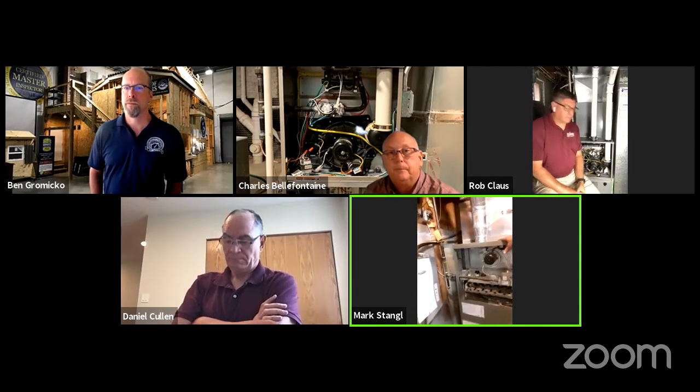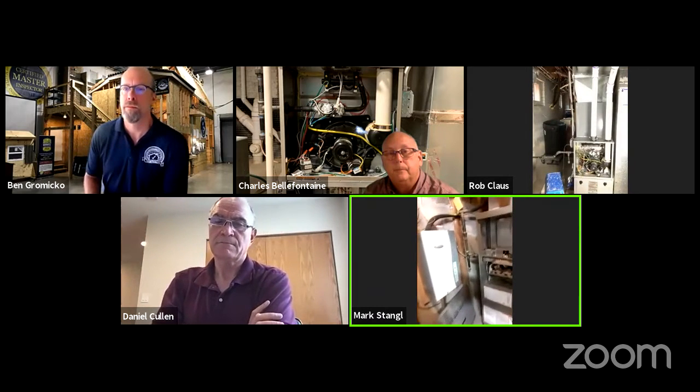I've already removed this front cover, and here you see the burners, and in this area you see the control system. It's not on now because you have the safety interlock switches here that turn everything off when you pull up this cover. So what I'm going to do is fire this thing up in just a second, go up and show you the thermostat.